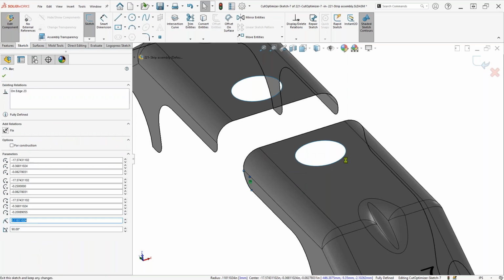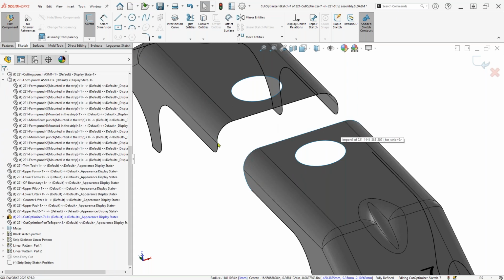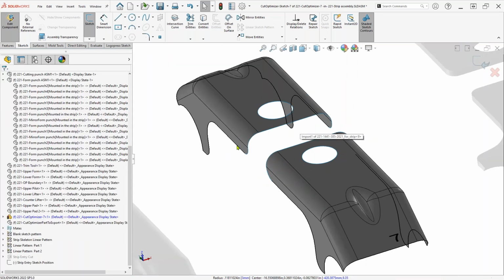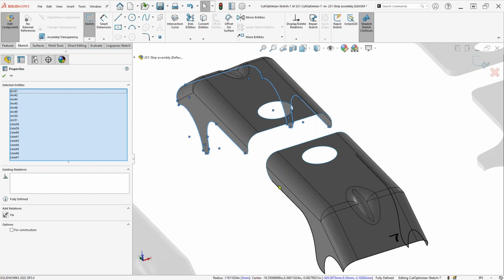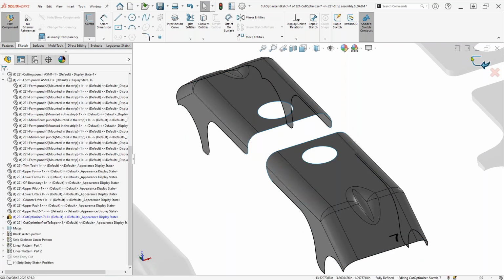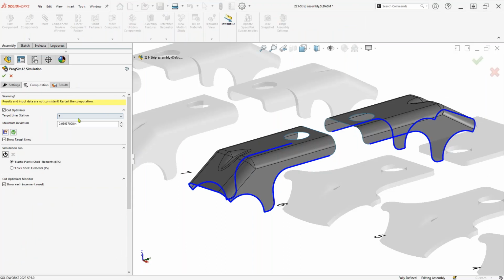You can also choose how far up the edge of the flange here, because it's going to be connected in the middle, so it can't optimize where it's being connected to the carrier yet in this station. But you can use this to work on just a little portion of the part if you need, one leg in particular you're working on, or if you want to optimize the part all at once. So we're optimizing just that blue portion. We're leaving the center alone.